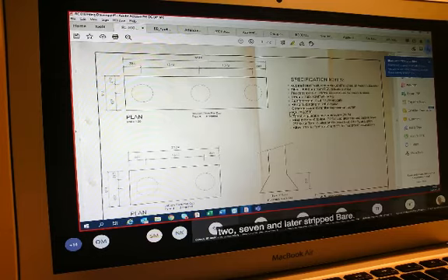If you have a look at what the drawing says, this is what we did. The piles we cast to the level 27427 and later stripped that. We're given that 28,500, which is ground level. It says that the piles are 600 millimeters from reduced ground level to the bottom toe.